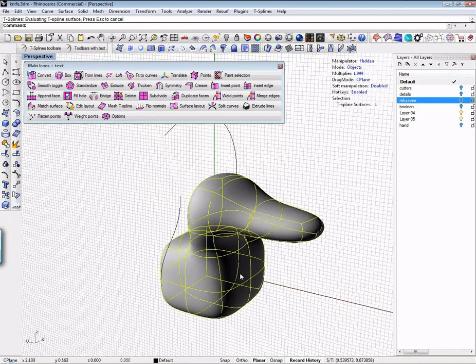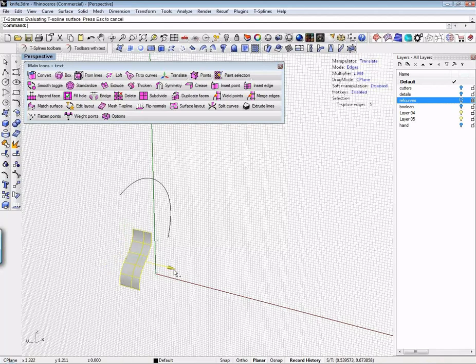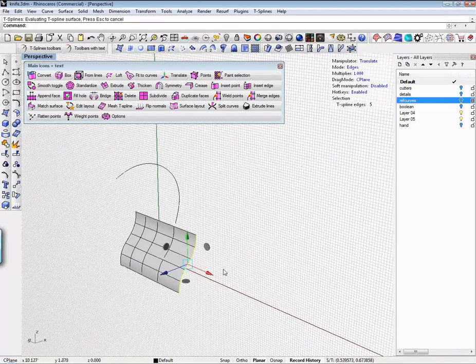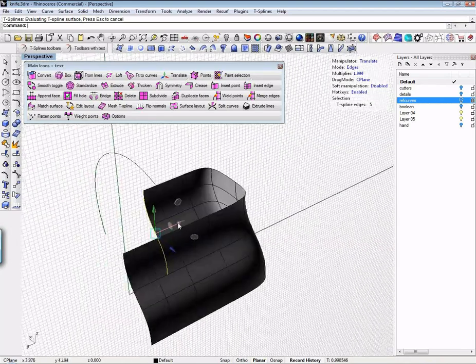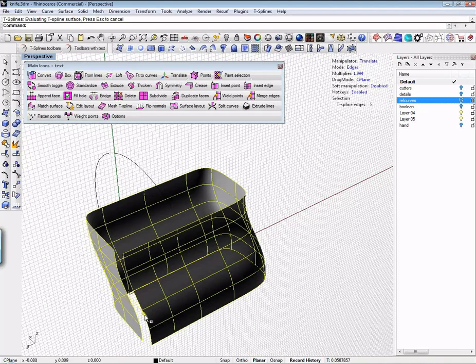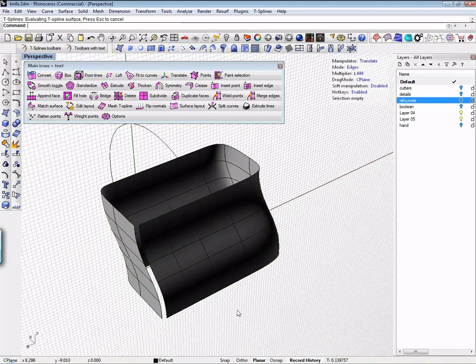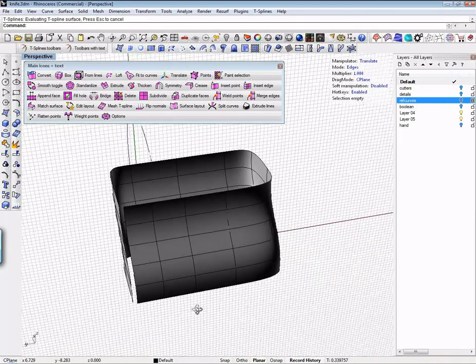The other way to work would be to start with some curves. And again, if I bring up my translate manipulator up here, if I click on one of these triads and I Alt-drag out, you'll notice that I can just kind of interactively extrude a curve. And one of the beauties of this is you can start making something by just Alt-dragging. So you can create some really awesome organic forms just off of a single extruded curve.